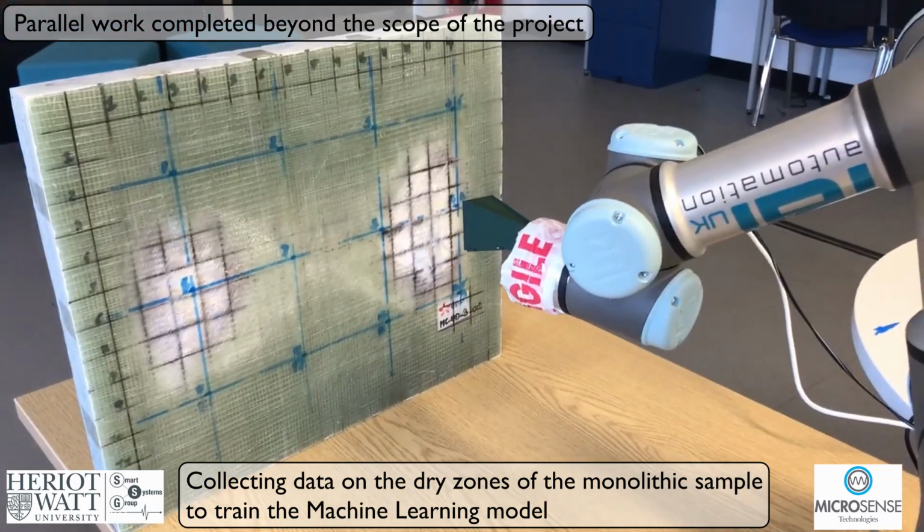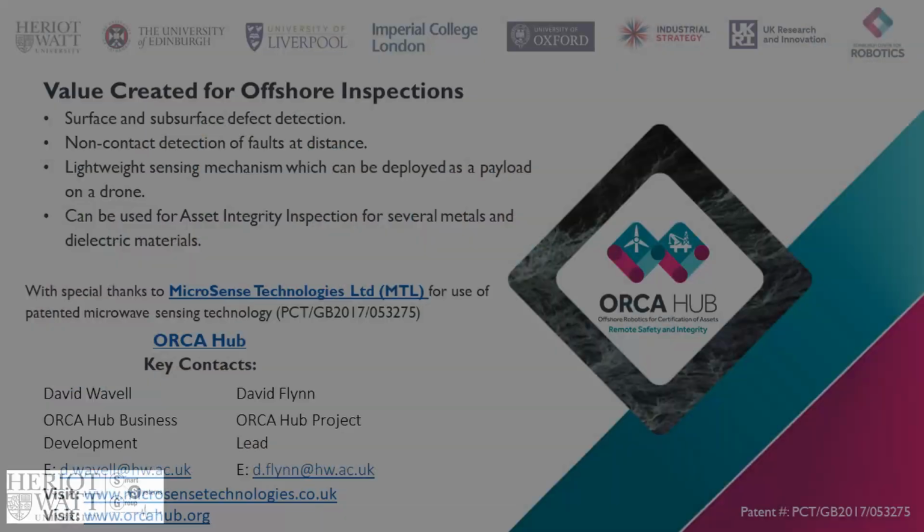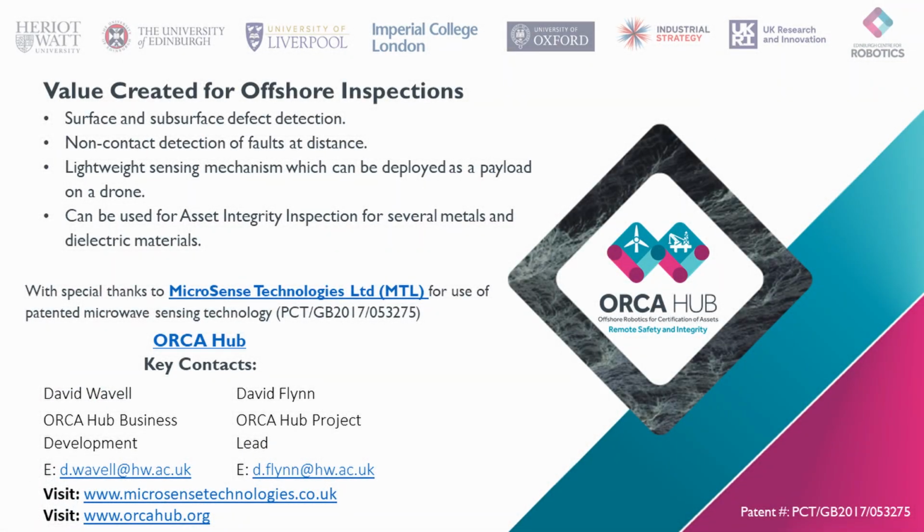A significant amount of value is created for offshore inspections due to FMCW radar sensing. This includes surface and subsurface detection of faults, a non-contact lightweight sensing method which can be deployed as a payload on a UAV, along with several deployment scenarios for asset integrity inspection, including inspection of surface metals for corrosion, and subsurface detection of wind turbine blades and civil